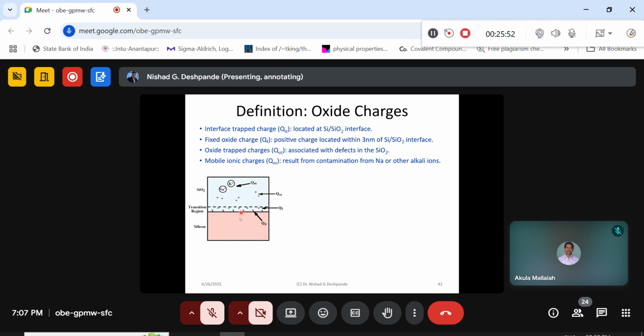Okay, and that's why whenever these trap states are formed, they contribute towards the avalanche processes. Maybe you have discussed this in the semiconductor physics part, what these avalanche processes are. And most of the time, high currents are possible, I mean leakage currents that are induced through the trap states here.